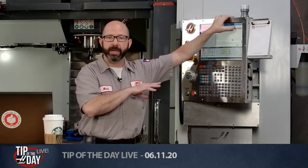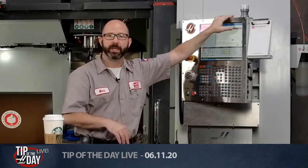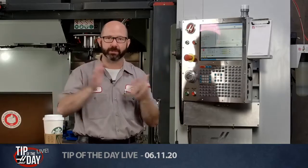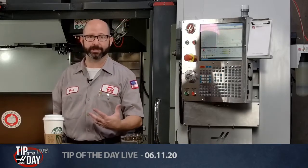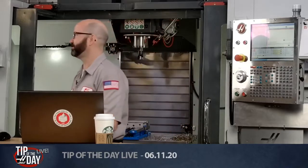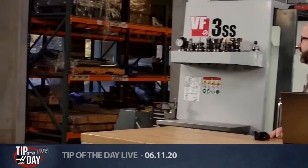Right now it's set to automatic because I want it to automatically change tools when I push buttons in my program. If you definitely do not want it to change a tool, because let's say it's really big and it doesn't fit in the tool changer or something silly like that, you can change setting 113 to manual, and it ain't going to do a tool change. So that's one bulletproof way to avoid tool changes. But the real answer is don't push the buttons. It's like driving a car. If you don't want to drive into the garage door, don't hit the gas. That's a great tip.